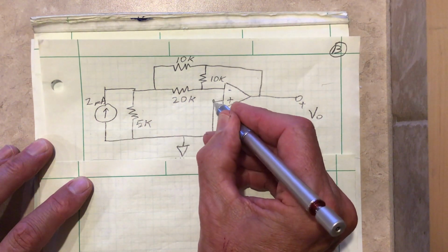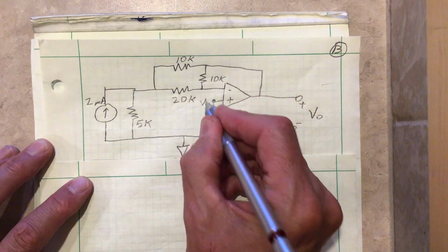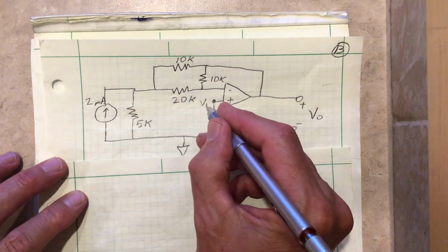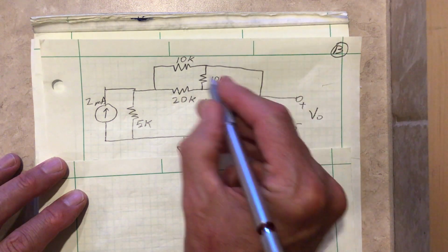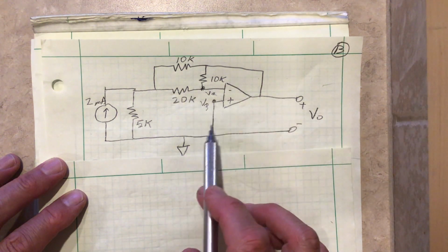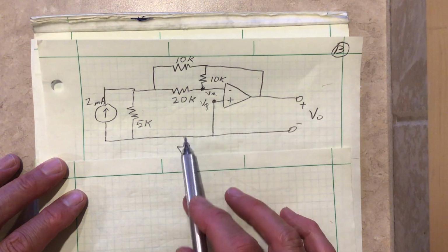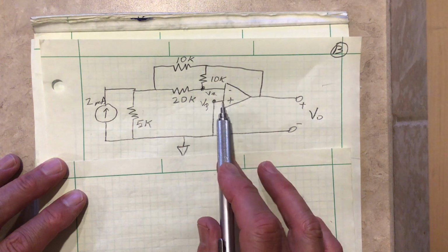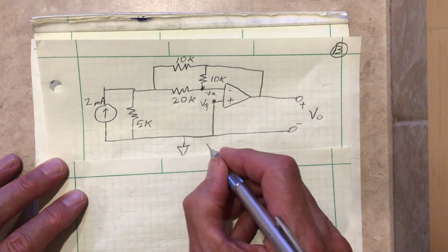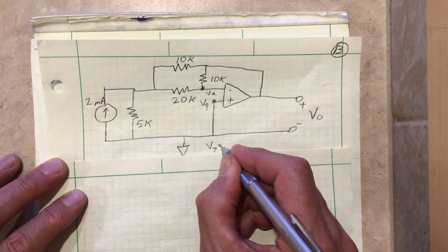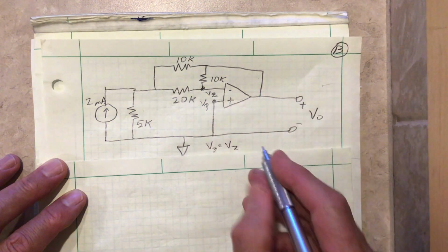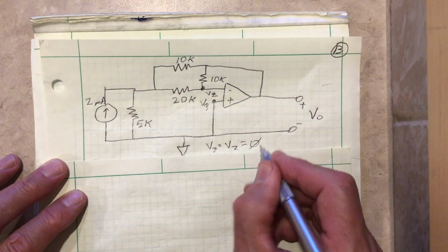That tells me that whatever my voltage is here, let's not call that V1. Let's call that V3. We'll see why in a minute. And this will be V2. And they're the same. So V3 is attached to ground, so we have 0 volts at the non-inverting input, so we must have 0 volts here. So V3 is equal to V2. That's a 2 right there. In case you can't read it, it is 0 volts.